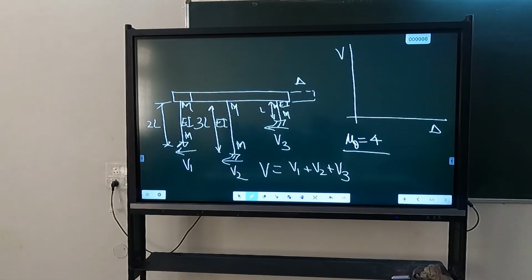Actually here 3 sets of hinges will form. First, the shortest pier will yield, hinges will form at top and bottom. Then the left pier will develop, the mid height which is having high intermediate height, that will yield at top and bottom, and then the tallest pier will yield at top and bottom.